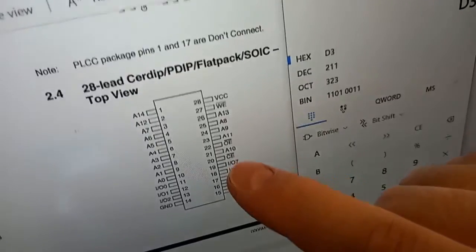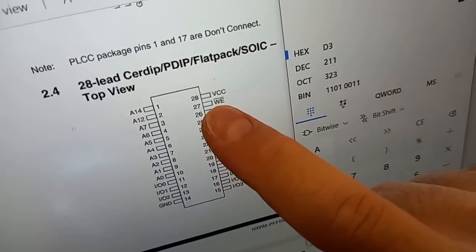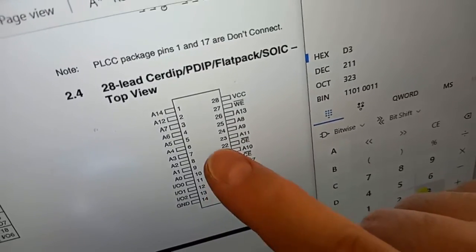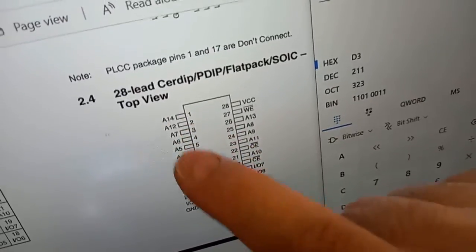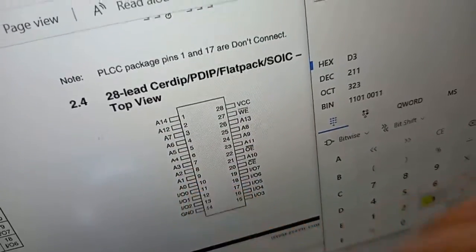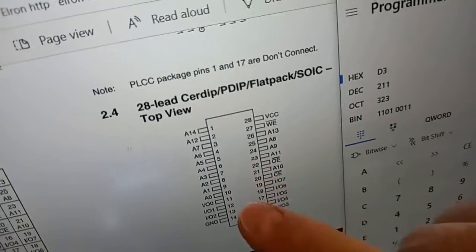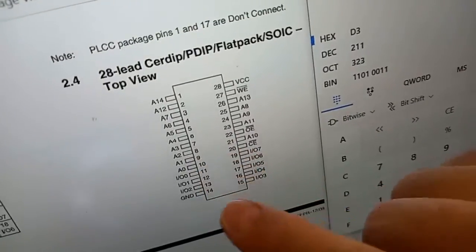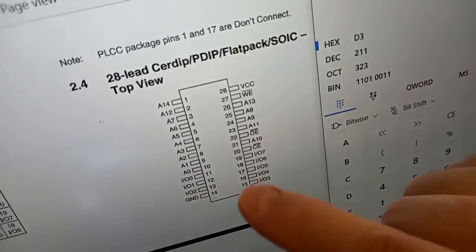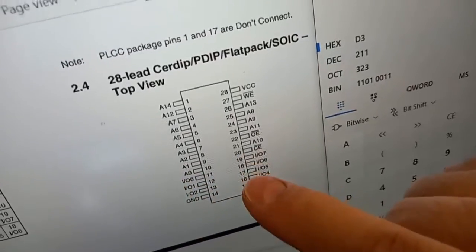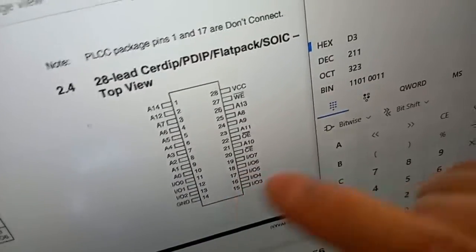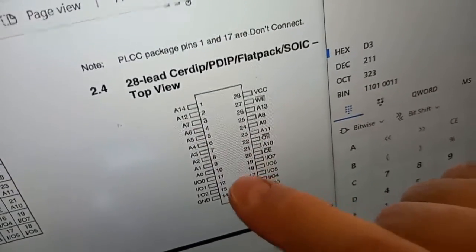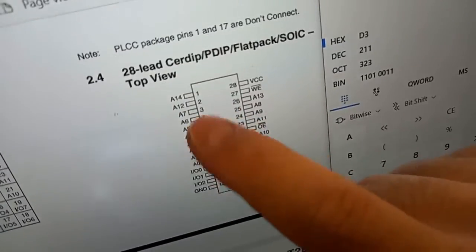And when we want to write something, we will enable this writing and we will disable this output. If we do that, then the memory will write to the given address that we can set here using ones and zeros. The memory will write to the given address, to itself, the number that it will find here. We will program this. Some we put to 1, some we put to 0, just like here. And then the memory will write this number that we set here at the data bus to this address.